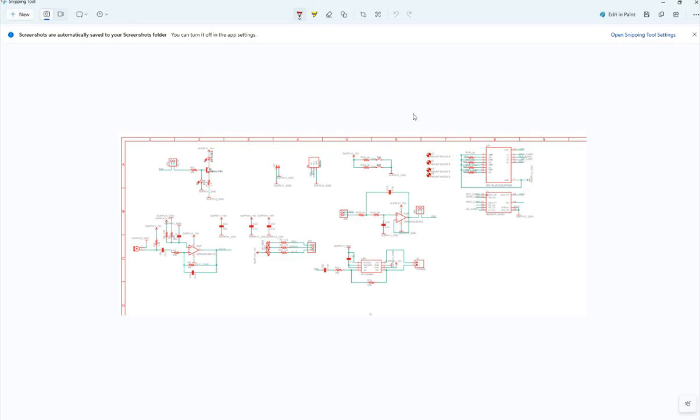Why double buffering? Because whenever this guy is filling up the buffer by digitizing, you are also writing the data to the SD card at the same time. But you cannot directly write data to the SD card using the buffer that is doing data acquisition at the same time. It has to be a different buffer.